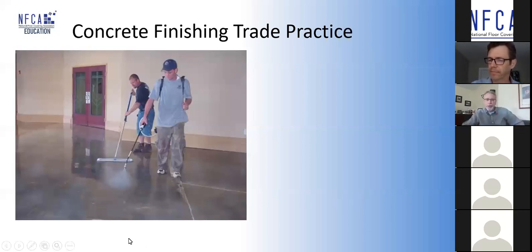So here you can see this corrective action is to meet the standard set, right? Correct. So this is the work that we're trying to do to achieve the F710 ASTM test. And this would not be the flooring trade's responsibility. It would be the general contractor or the concrete sub-trade's responsibility. It's specified in Division 3 because it is concrete finishing work. It can now be identified in the specification; it was never identified previously because there was a lack of a description for it, basically.